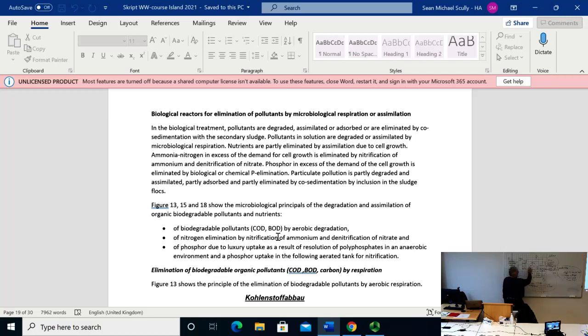And now we look first at without nutrient removal. So we have our microorganism. He is consuming 40 grams of O2, 50-50, we just assume. It's not exactly 50-50. There's formulas for that to calculate that more explicitly. And the rest, the 40 grams COD, will be assimilated.